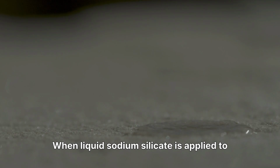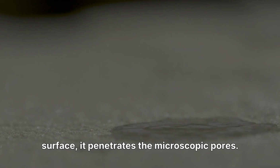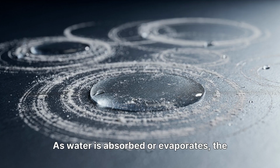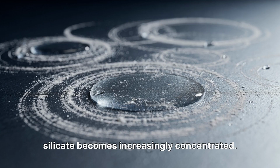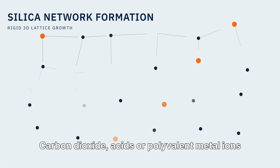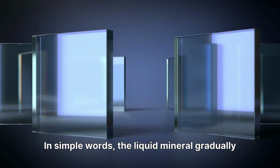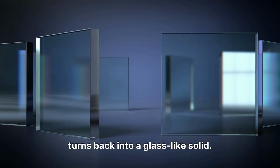When liquid sodium silicate is applied to cardboard, wood, mineral fiber, or another porous surface, it penetrates the microscopic pores. As water is absorbed or evaporates, the silicate becomes increasingly concentrated. Carbon dioxide, acids, or polyvalent metal ions can further trigger the formation of a rigid silica-rich network. In simple words, the liquid mineral gradually turns back into a glass-like solid.